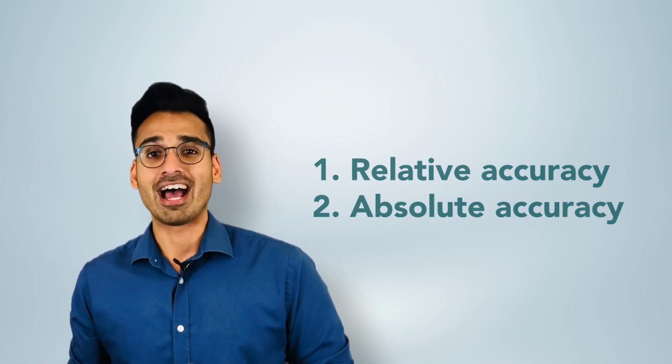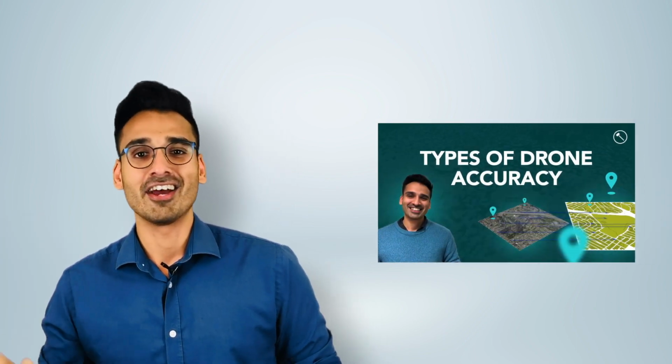We talk about accuracy of drone data in a separate video, so I'm going to link that here and feel free to check that out after this video. But essentially, measurement accuracy and georeferencing accuracy are two different names given to relative accuracy and absolute accuracy. The simple fact of the matter is that if you want to take measurements from your maps and models after you process the data, those measurements can be very accurate, but it all depends on the GSD you use to capture that data.